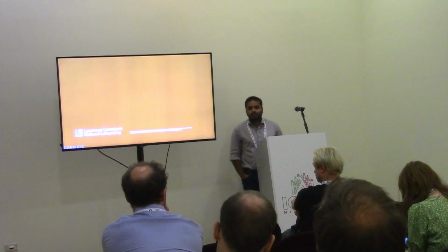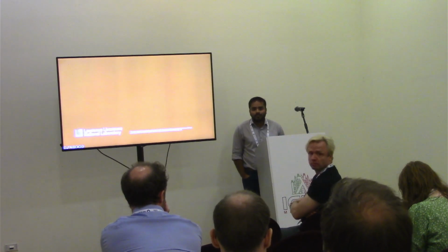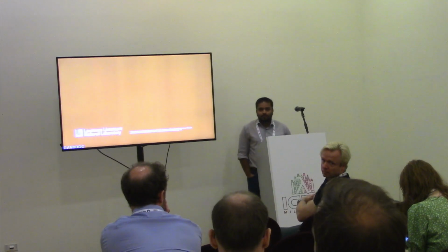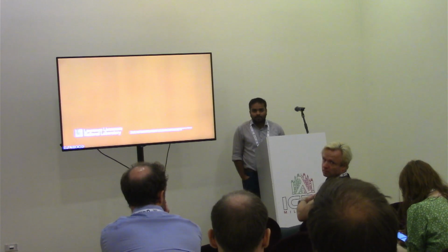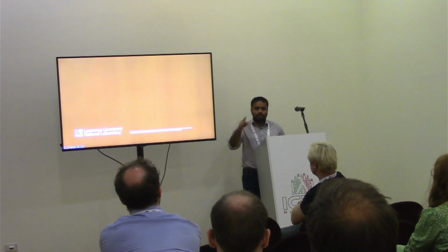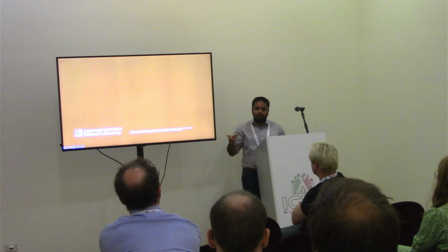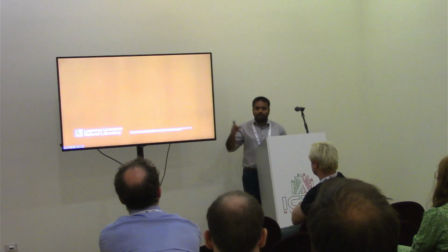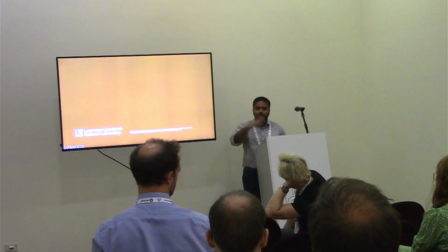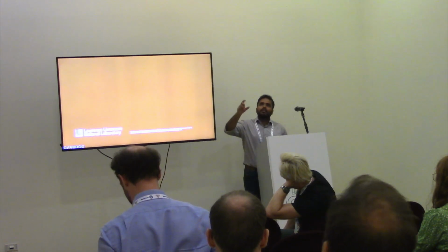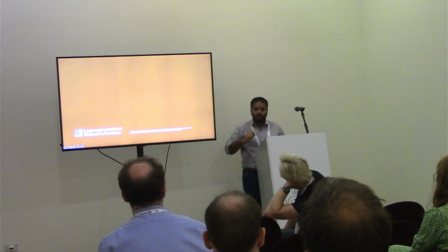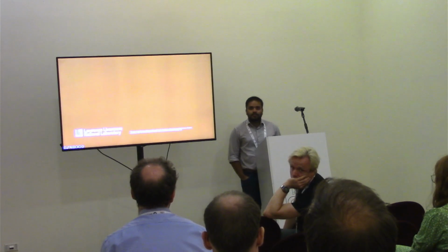So I'm wondering if this approach is also applicable to subtractive manufacturing, because I would expect subtractive manufacturing to be more difficult than additive manufacturing. Right, both subtractive and additive manufacturing have the same style of writing. The NGC, ISO 6983 language, that same language is also used for conventional subtractive manufacturing. So this analysis can also be extended to subtractive manufacturing because they have the same flavor of writing. Even some of the G-codes have the same semantics for both conventional and additive manufacturing. Yes, but I'm not sure.